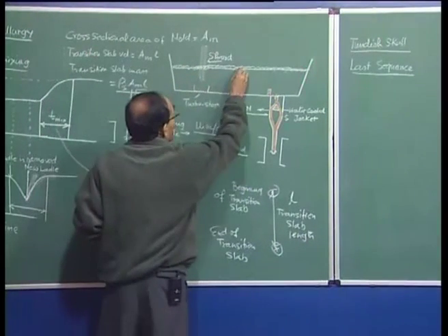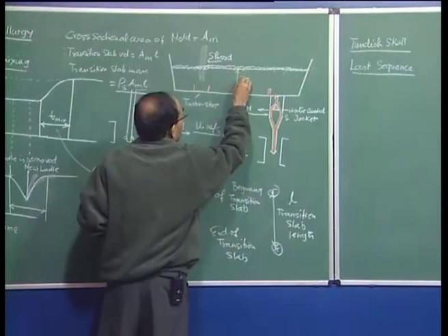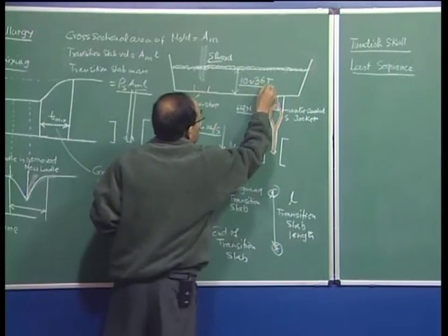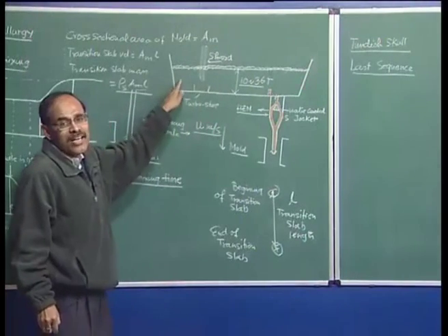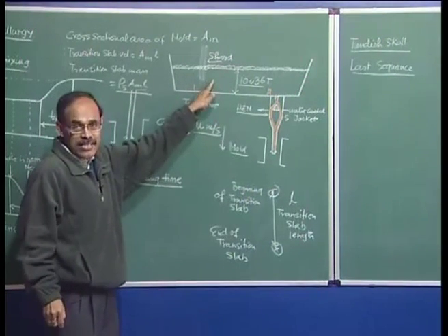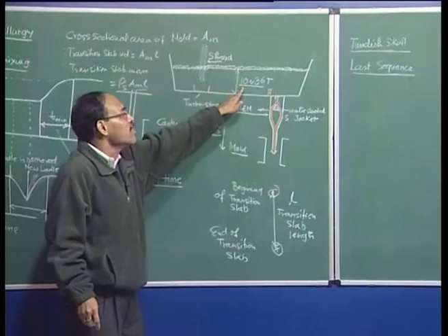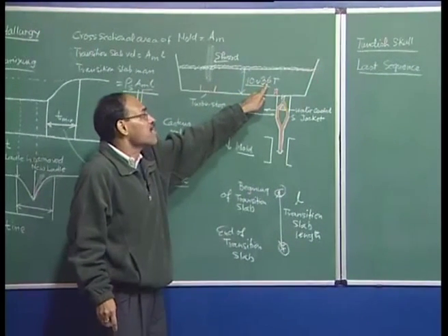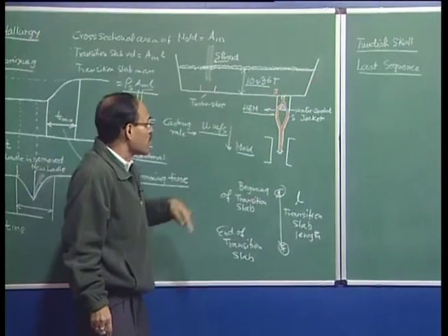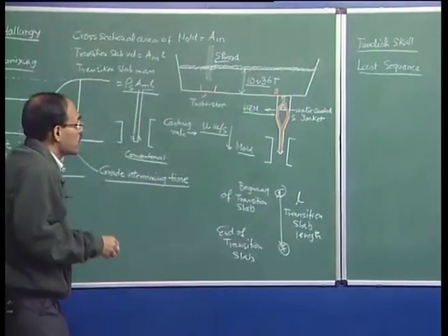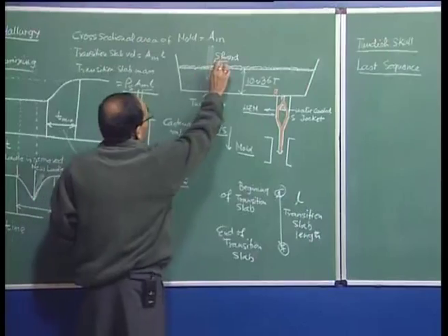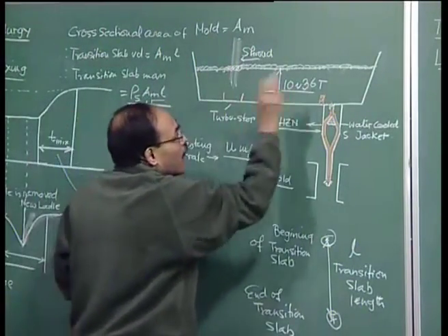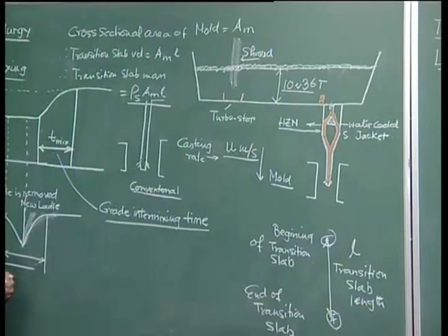We have about 10 to 28, maybe 10 to 30 tons, I have seen so much of material. This is the mass of steel in a tundish. So, this could be in a bloom casting tundish, and this could be in a thin slab or a slab casting tundish, a huge slab casting tundish. They can contain about 36 tons of material. So, the moment molten steel from the ladle is stopped, we have about 36 tons of steel remaining.